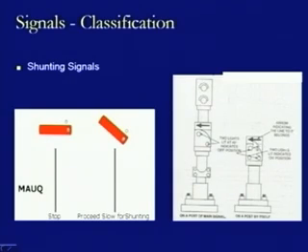The arrow which is provided at the top here indicates the line to which the shunting belongs. This is how it defines. Whereas in this case, the post is increased in further height, and it is provided with the color aspect signal at the top. So, we are using the same signal as a main signal as well as a shunting signal. Both are provided on the same post, and that is a combination of the 2 signals.